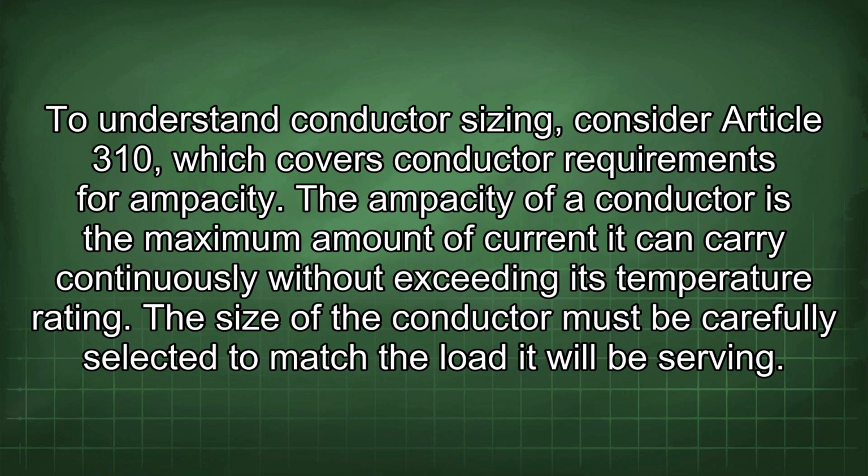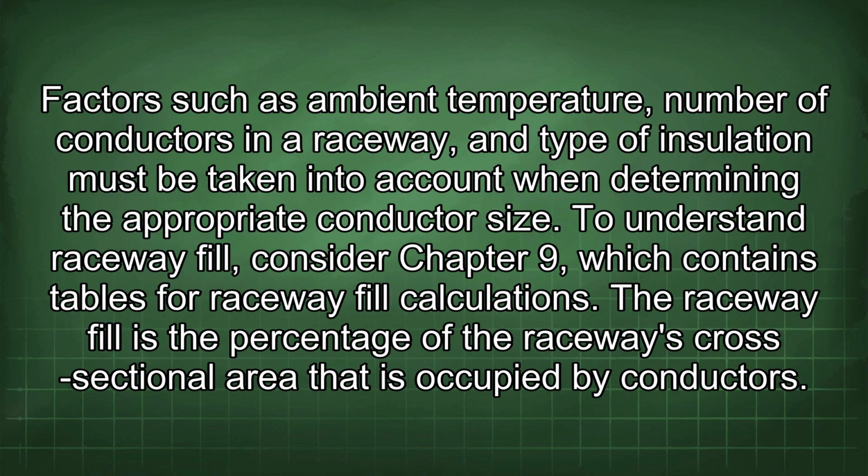To understand conductor sizing, consider Article 310, which covers conductor requirements for ampacity. The ampacity of a conductor is the maximum amount of current it can carry continuously without exceeding its temperature rating. The size of the conductor must be carefully selected to match the load it will be serving. Factors such as ambient temperature, number of conductors in a raceway, and type of insulation must be taken into account when determining the appropriate conductor size.